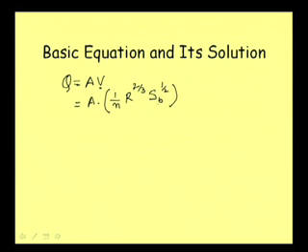Again I am repeating that SB is used because we are talking about uniform flow. Then what is R? R is nothing but A by P. So, we can write A, then 1 by n, then A by P to the power 2 by 3 and SB to the power half.